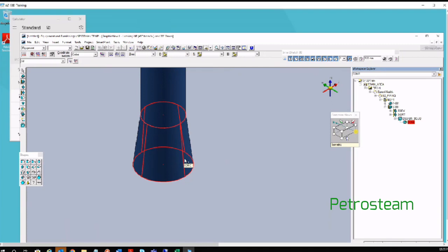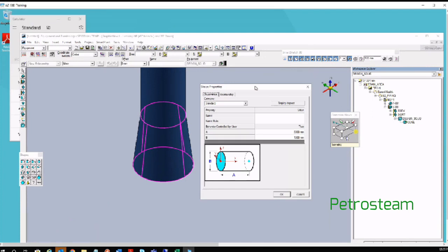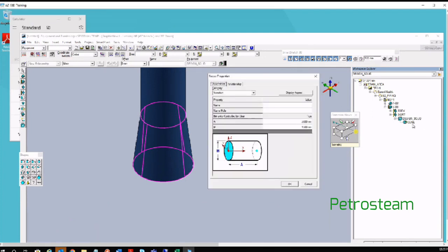For that, if you need a hole, that's nothing but a circular shape. To make it, I have to place a cylinder as the circular shape and make it negative so that it will cut through this positive cone. For that, within this design solid only, I will place a cylinder, similar to this cylinder. Now next shape, cylinder, by selecting the design solid. Make sure you are placing a positive shape and a negative shape within the same design solid.